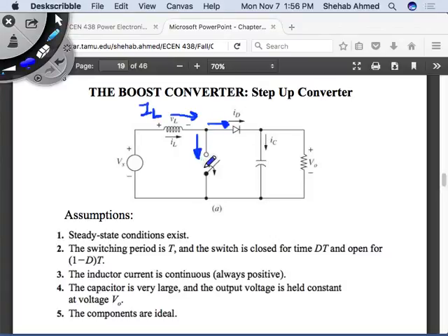Is it half of IL? Exactly. So what is it? Remember, what is the current that will flow in this device? How will it look, approximately? When the device is on, there is current. When the device is off, there is no current. Fine, there may be some ramp to it, but forget about that. Assume it's a square wave.